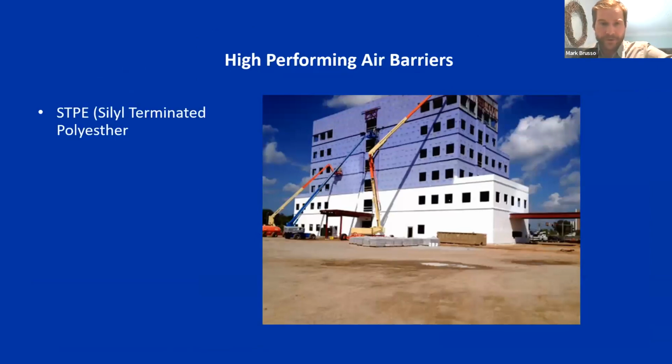As I had mentioned earlier with the Air Barrier Association of America technical data, the high-performing air barrier is also a very important component of the rain screen system. The air barrier is managing your air movement and controlling air leakage in and out of the building envelope. Although the air barrier's primary function is to regulate air leakage, it also has a very important secondary function as a water resistive barrier. So if water does get in behind the primary cladding, which is supposed to shed water, and there is drainage occurring, this barrier is also waterproof, so it's not allowing any water into the interior components.